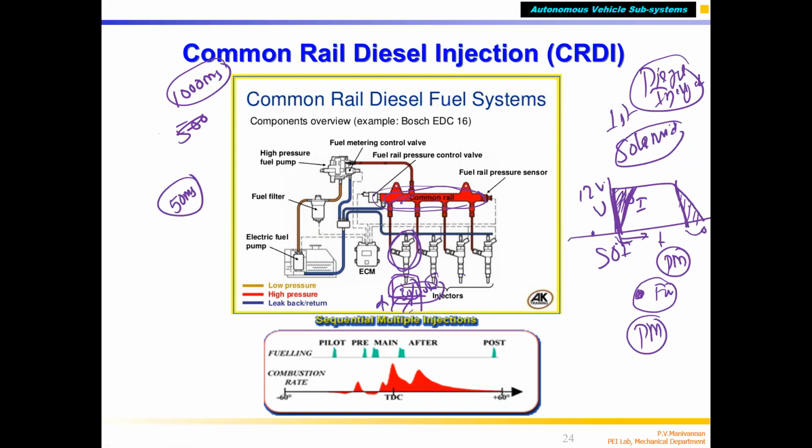When you take a small quantity of fuel from the reservoir, this is nothing but a fuel reservoir. It is now stored at high pressure by the pump. Now, from say 1000 milligrams, if you take 50 milligrams, how much fuel are you taking? Only 20 times less. Then if you take less fuel from your high pressure reserve, the pressure drop will be less. So the 1,500 bar pressure will be close, it will be maintained.